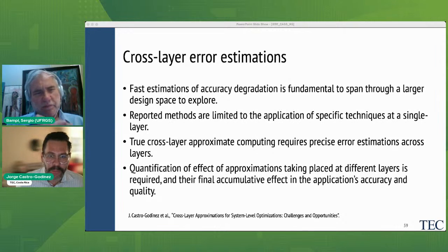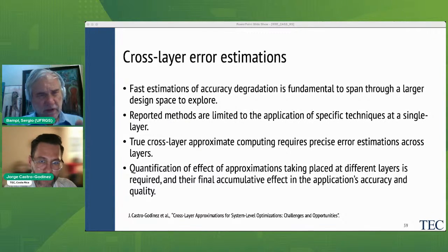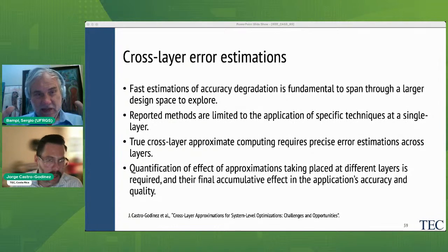If you allow me to make a point, if I were to explore the HLS, first I would do the precise architecture and do the exploration at the precise level. And once I'm comfortable with the trade-off between PPA, performance, power and area, then I would take that HDL generated by HLS and then apply more conventional approximate computing techniques. Indeed, you are more likely to get better results. Indeed. Okay, that's my advice to students and people listening to this talk.